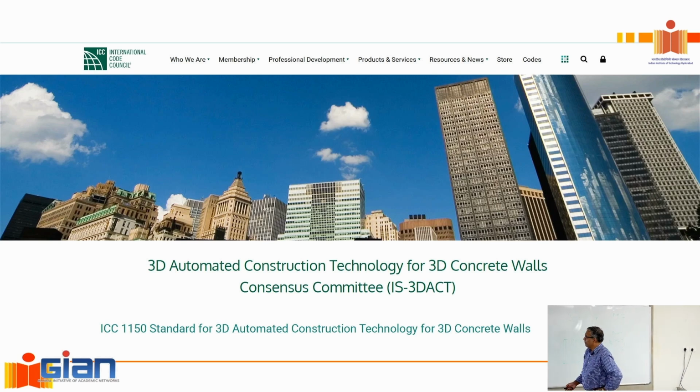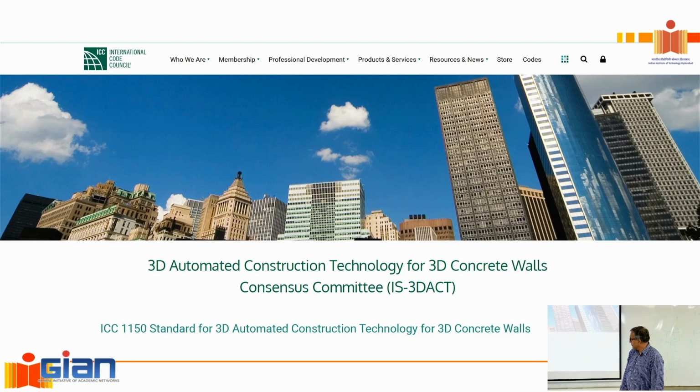Last few slides where I present to you, currently there are no standards for printing, but this is the closest we've gotten to a standard. The ICC has put out a standard for 3D automated construction for 3D concrete walls. Okay, it's available. You can download it. You can look at it for guidance when it comes to structural use of this as walls. The problem there is that they really don't give you anything in the form of an equation that will help you design anything, because they're fully aware that the same concrete that is printed using your printer or mine will be very different. What they do is they guide you, saying that, look, you can follow this process.